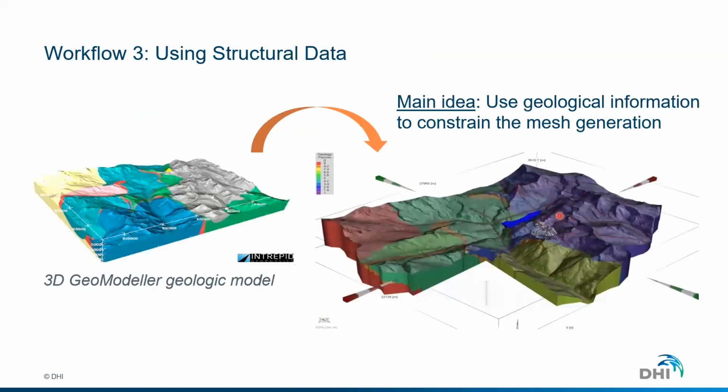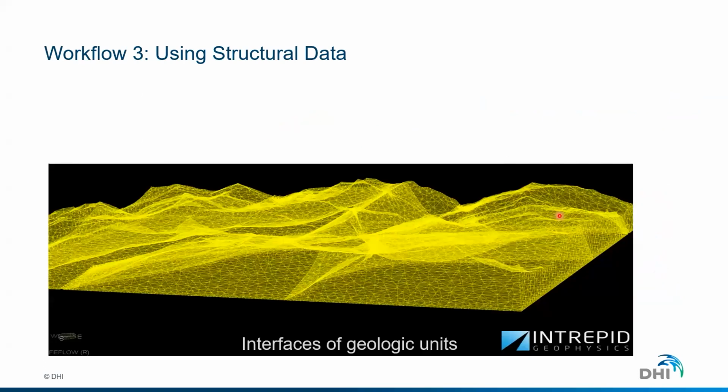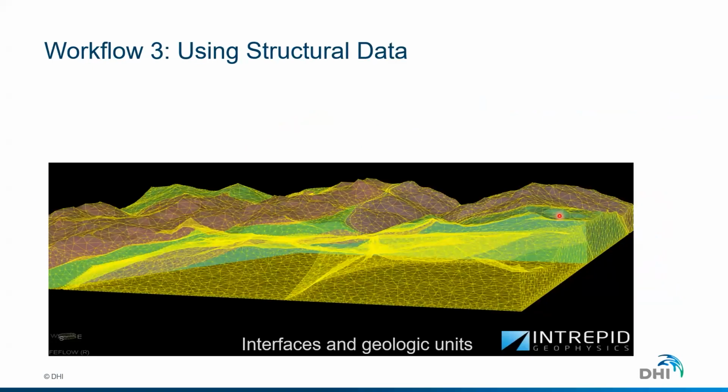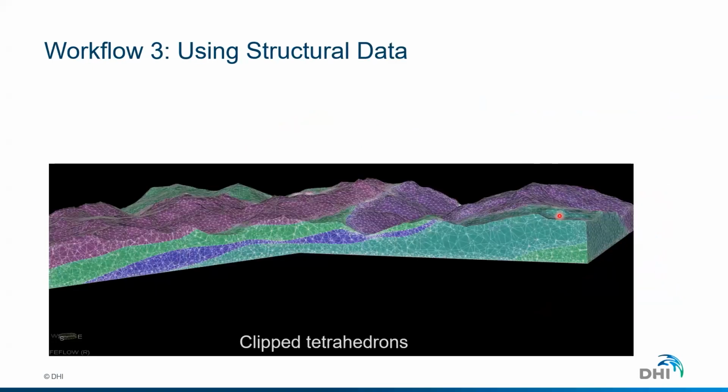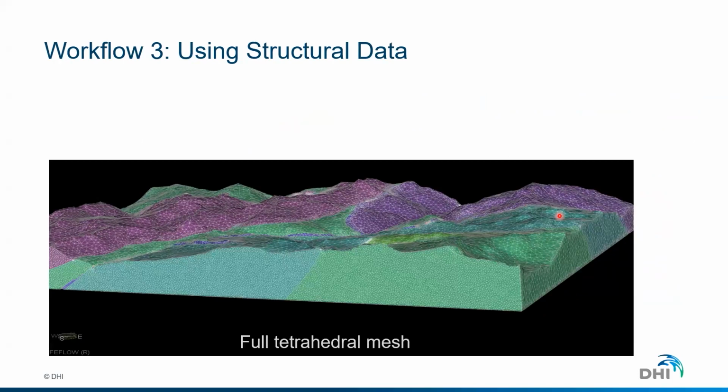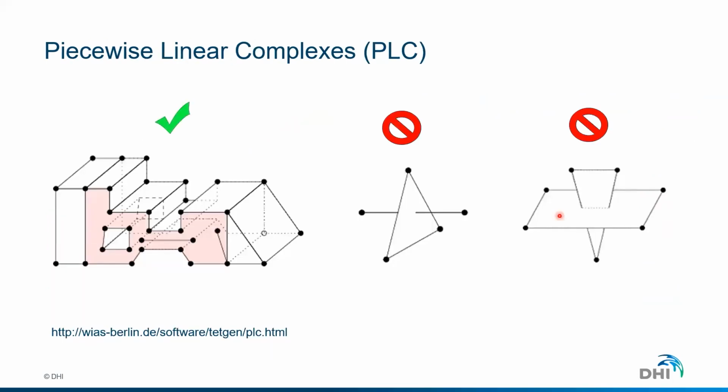As I said before, the motivation is to try to put most of the information into the FEFLOW model and not simplify the geological model or the conceptual model in order to fit a limitation of the software. No? So we try to get as much as possible of the data. So this is an example done with GeoModeller 3D, where you can see the different structures, the tetrahedrals being clipped by the planes in FEFLOW and the fully 3D model.